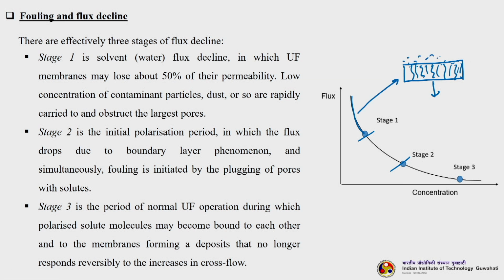Then slowly the concentration polarization or boundary layer build up will start. So, this is the boundary layer build up, which is happening in stage 2. So, fouling is initiated by plugging of pores with solutes. The pores will be plugged with solutes which are either mostly similar in size to it or smaller than it. So, stage 3, this stage, is the period of normal flow operation.